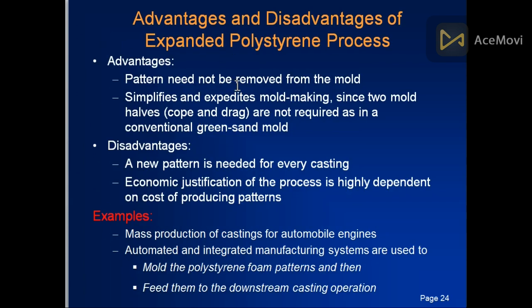Advantages: the pattern need not be removed. We don't need to remove the pattern. It simplifies and expedites mold making. The mold making is very easy. Disadvantages include that a new pattern is needed for every casting. We need another mold and another pattern for each casting.